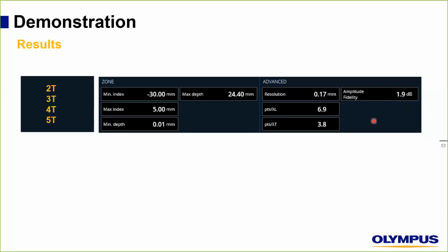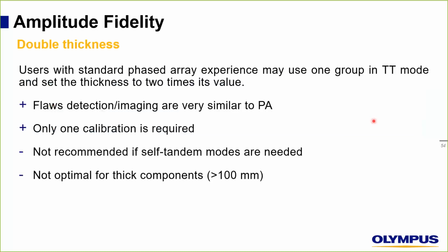So multi-groups won't affect your code compliancy if you do the zone selection well, if you select the right wave modes for your detection and sizing, etc. Of course, multi-group will improve your inspection, not to the contrary.